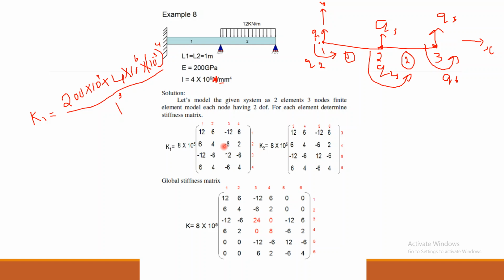So once this is done, the next part is the representation of the nodal degrees of freedom or global connectivity. For element 1 consisting of Q1, Q2, Q3, Q4, I can represent 1, 2, 3, 4 here itself, 1, 2, 3, 4 for each row and column.